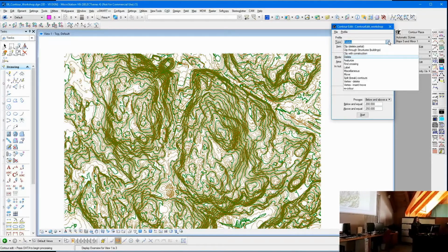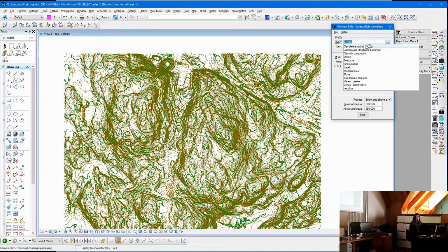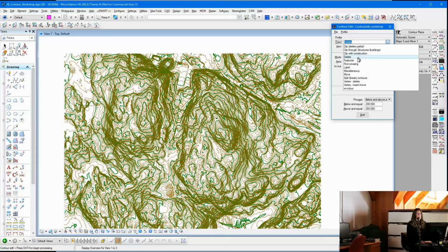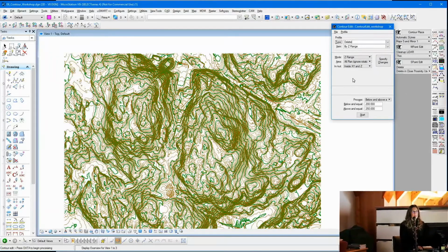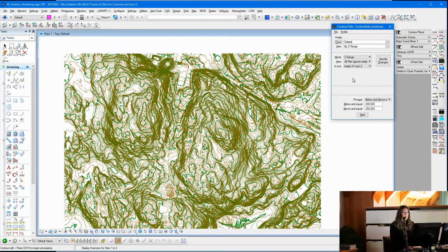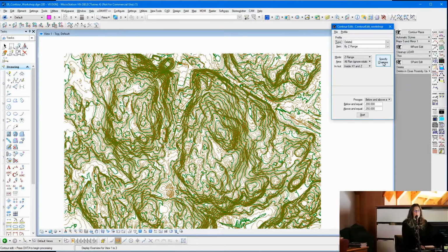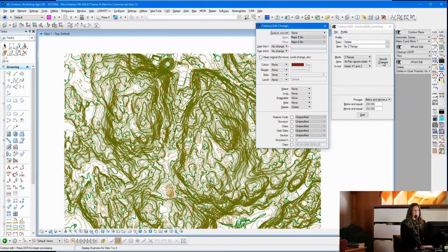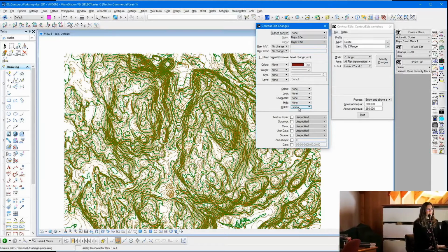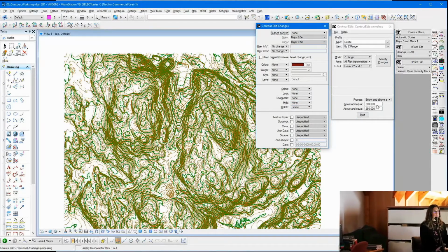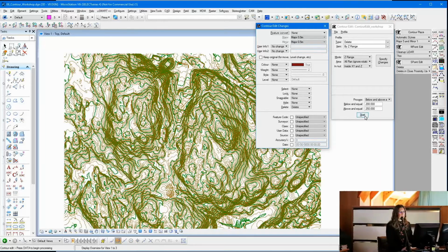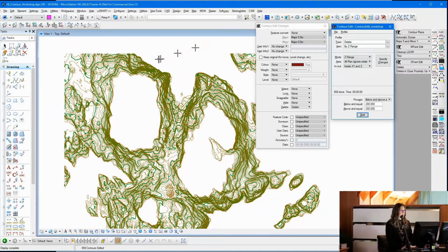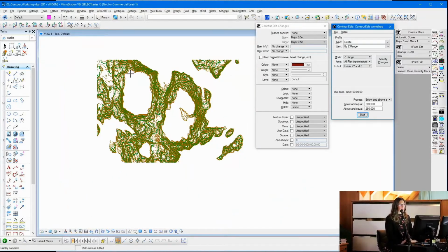So this is pretty much what you're going to get. We might add 1 or 2 after this. So we've done all the clipping stuff. I'm not going to go through that. I'm going to show you a delete. So we're going to delete by Z range. So over there we chose Z range. And if I show you how I'm getting to a delete under specified changes, I'm just choosing to delete. Okay, and I'm going to delete everything below 200 and above 250. And there we go. All right, as quick as that.